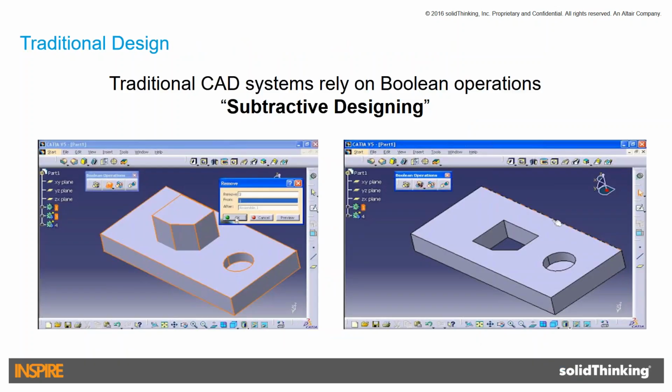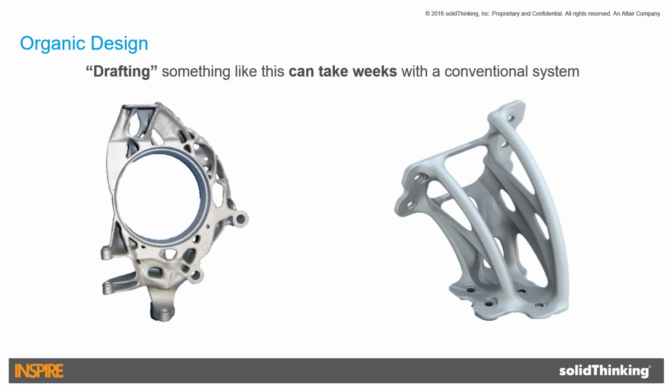So topology optimization really gives me the freedom of designing a part. Let's take the example of a CAD system. CAD is basically a 2.5D tool, where we sketch something, extrude, protrude, and do Boolean operations to create a design. But how about a design like this? Can we design this using CAD? Possibly, yes. There are really good CAD users with very high skills in surfacing and surface modeling. But what we see on the screen can be modeled maybe in days or weeks of time. What we are saying is, using Inspire, come up with these designs from the very first time as your concept, model them using some of the very powerful tools within Inspire called PolyNURBS, the surface modeling, and get it done in a day, less than a day, I would say.